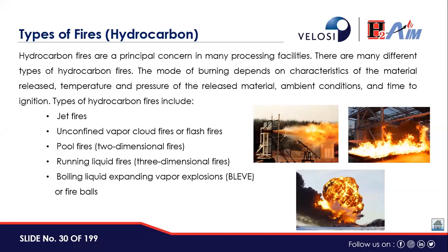And pool fires are like if a liquid from the tank leaks into bunds or a dike, and if the fire is there, then this fire would be like a fire in a pond or, you can say, a swimming pool. That kind of fire is called pool fire. Then unconfined vapor cloud fires or flash fires can also take place. Running liquid fire, like in an open channel, could be a running liquid fire. Then boiling liquid expanding vapor explosion, which is BLEVE, or fireballs.